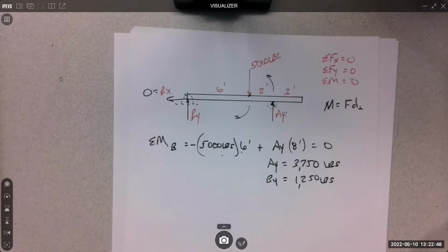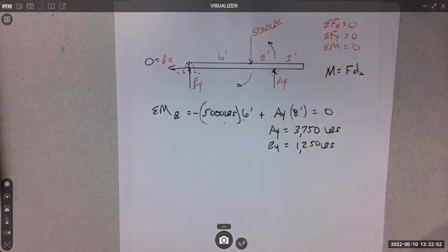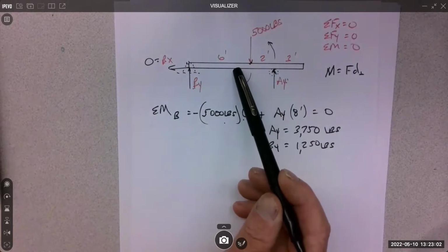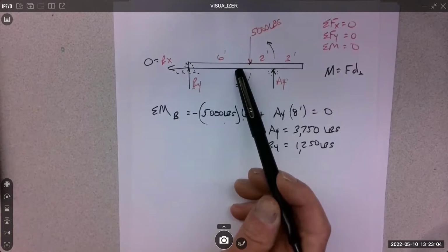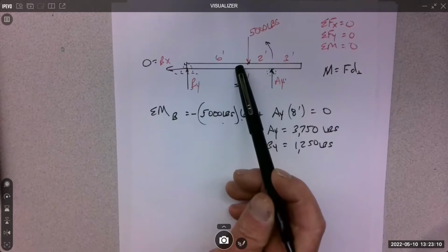That's good. All right, so now beyond statics is bending moment. Like this thing's gonna deflect. It has 5,000 pounds on it. I don't know what it is, right? I would need to know what it is to calculate a bending stress, but I don't need to know what it is to calculate a moment, an internal moment.